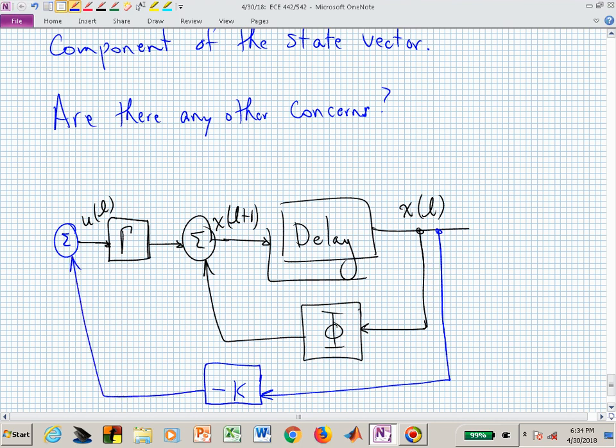And what we've done so far is we've told our system how to behave. If it's controllable, we can use full state feedback. We go in and access the state vector and feed that back. The output is right here. But now we want to influence where it goes. And now I'm running out of room on the left. But I want to introduce a reference input. And that reference input, I now want to scale by n sub 1.